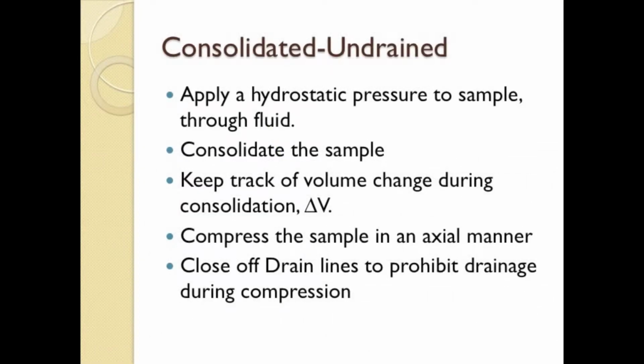A consolidated undrained triaxial test is an axial compression test, but confinement is taken into account. Starting with the test name, consolidated undrained means the sample is fully saturated and consolidated, and undrained means the sample is not allowed to drain throughout the test.